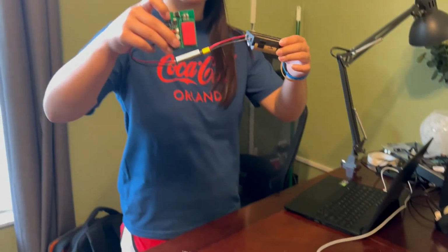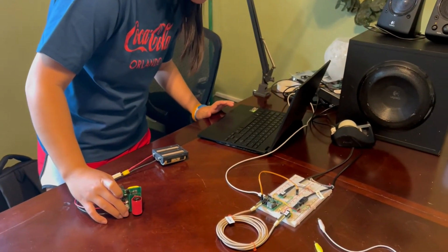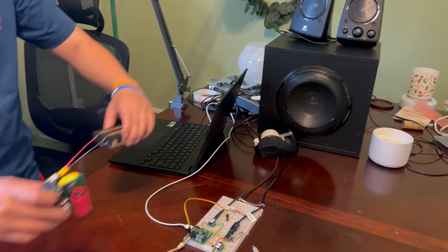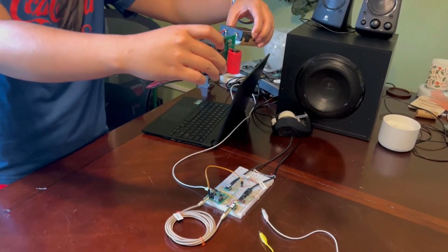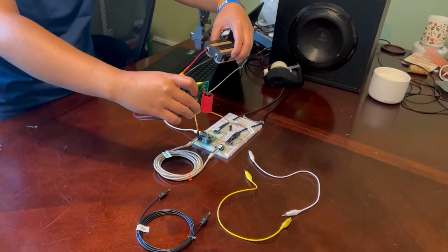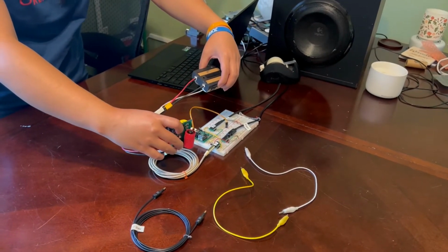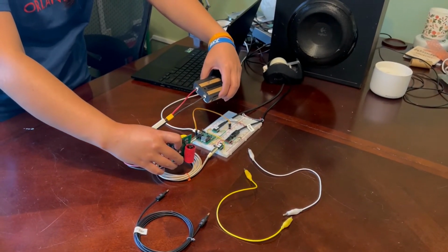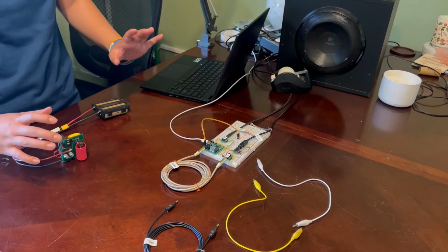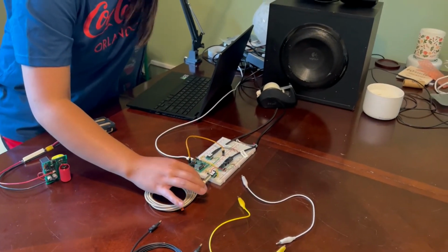So now we'll start out with the analog signal with the copper wire. Here's the interference generator we will be using. I will be bringing the interference source close to the coiled cable, which will increase the B field, and that also increases the induced voltage, which in turn increases the noise in the cable. The circuit is vulnerable to external interference, even using the shielded copper cable. And that's why you can hear the 5 kilohertz frequency.